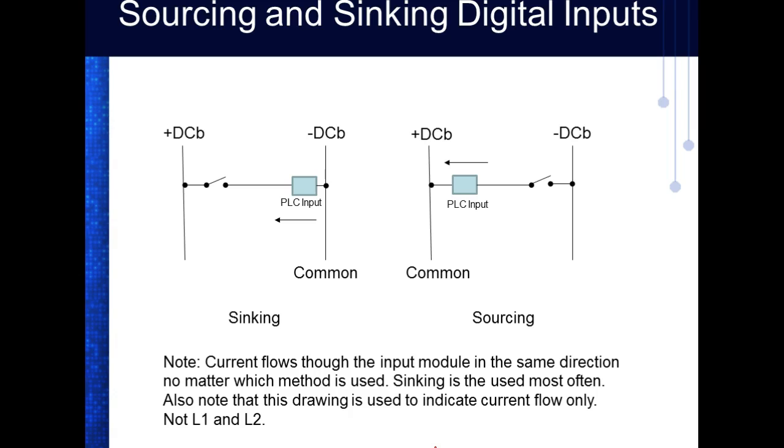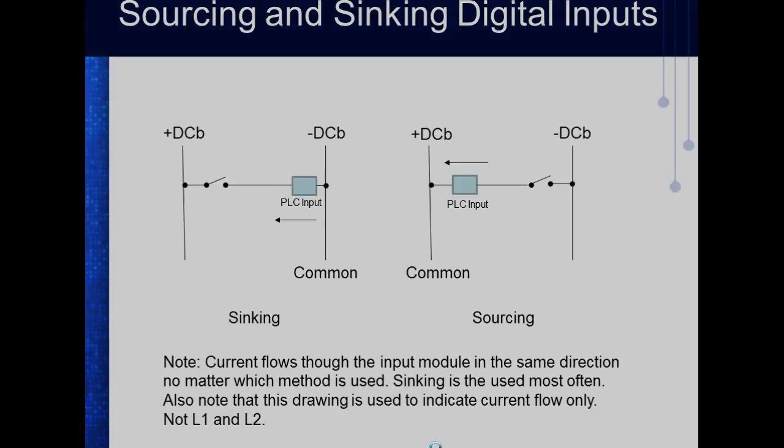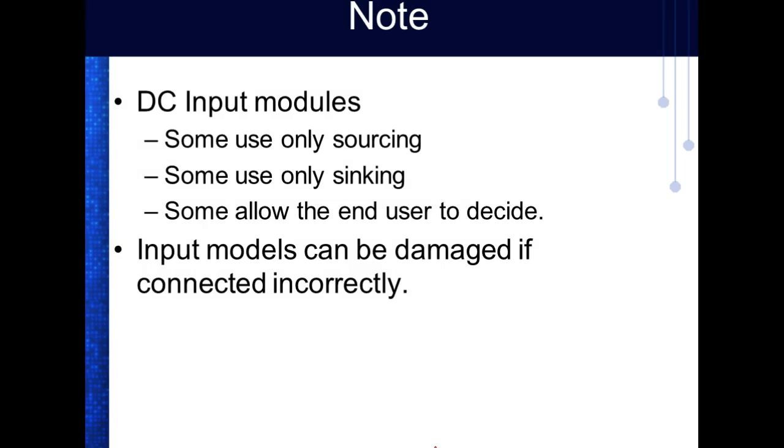So it's very, very important that you know that. When I go out there and look, I can't remember what the inputs are. I think the inputs for the 504 are sinking inputs, so those can't be changed. And I think the outputs are sourcing. Some use only sinking, some use only sourcing, some allow the end user to decide. And of course, more and more they're moving to what? Number 3.